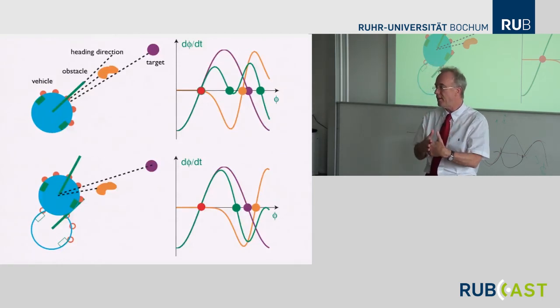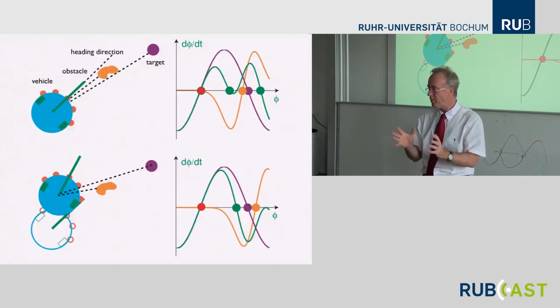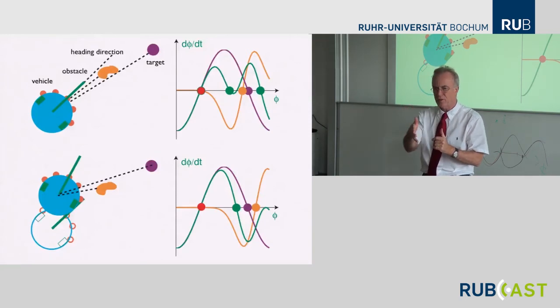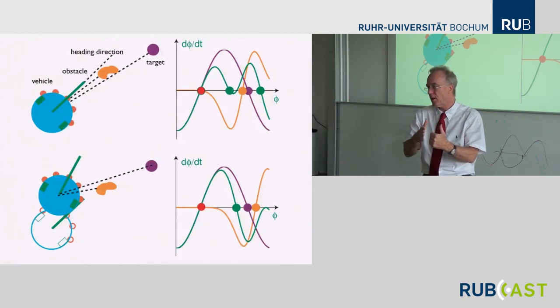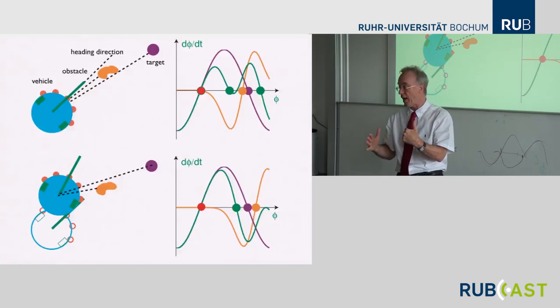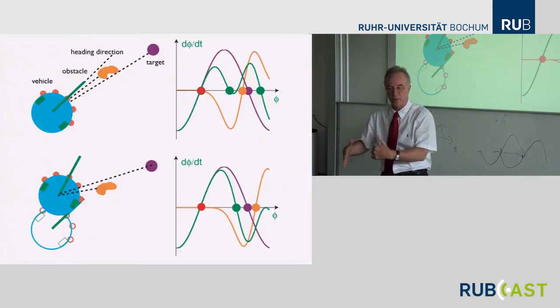And so in practice, the cascade is like this. You compute as fast as you can. That includes a lot of the sensory processing. These infrared sensors in these simple vehicles actually need some stabilization time. They are very bad. But in later vehicles, the main problem is vision. We do everything with vision later. Vision is very computationally expensive. It takes some time to compute that. That makes the minimum update rate, and that makes how steep we can make the dynamics, and that makes how fast we can drive. We can only drive slowly enough for that tracking to happen.